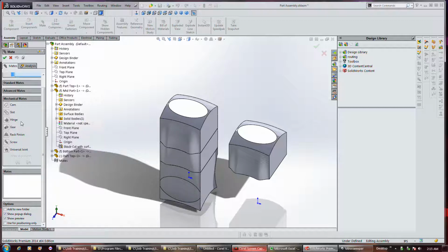For example, I could simulate the motion of a hinge without a pin in it. So if you didn't even have a pin in it, I can make two halves of a hinge actually act like a hinge. But of course, in practice, it'd be better to actually have a pin in it and then establish relationships with those mechanical elements so that the hinge works right. But you can kind of mock it up with this.